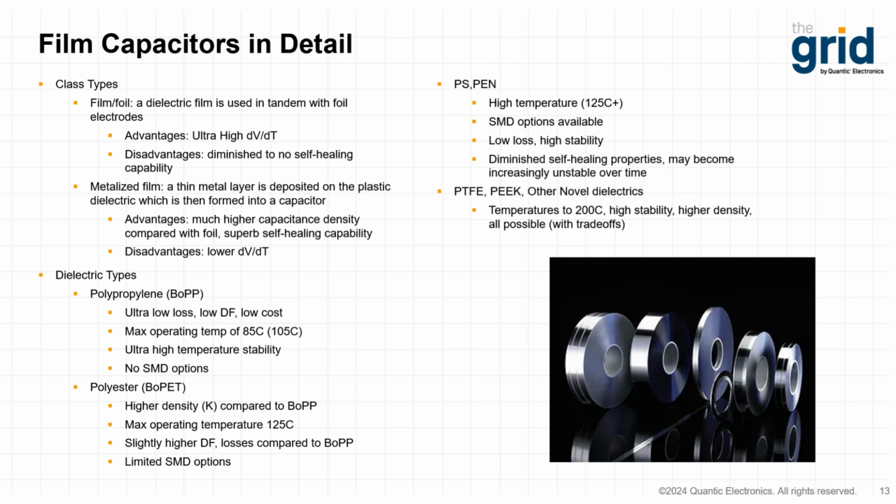K values of plastic dielectrics are significantly lower than those of barium titanate-based ceramics, but they make up for it by having thinner dielectric layers, resulting in comparable densities at the end product point. While ceramics have very high melting points, plastics obviously are much less forgiving in general. These fundamental differences make for the unique advantages between film and ceramic. The two main types of plastic capacitors, film foil and metallized film, will be discussed first.